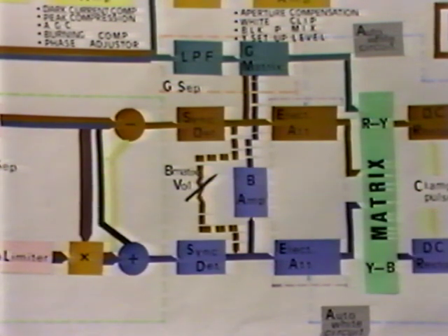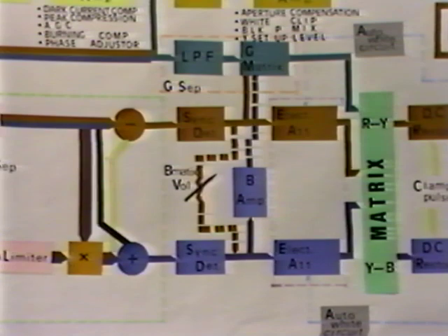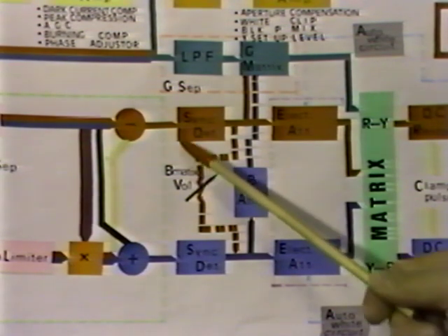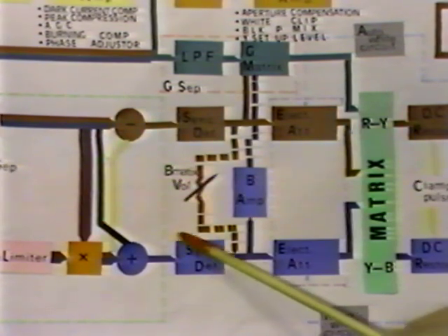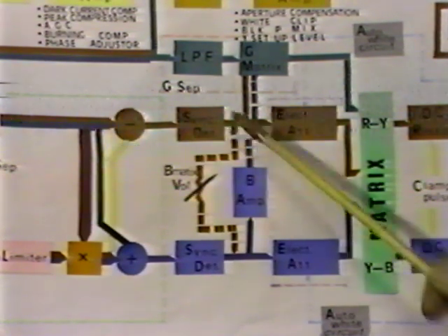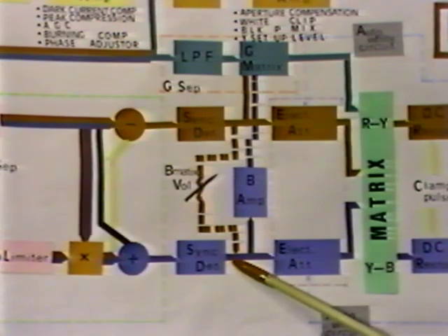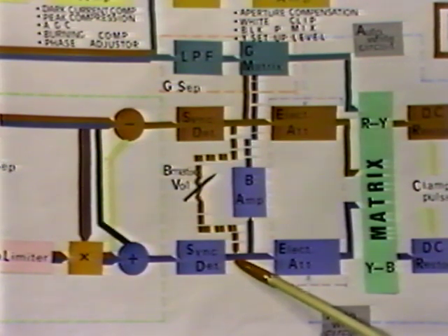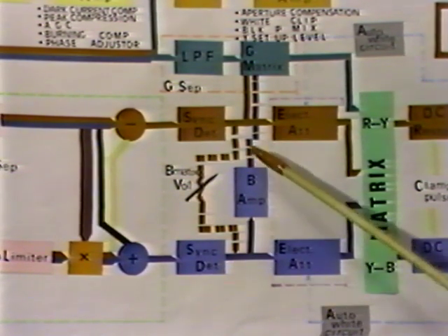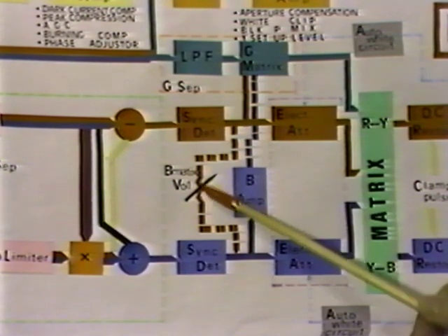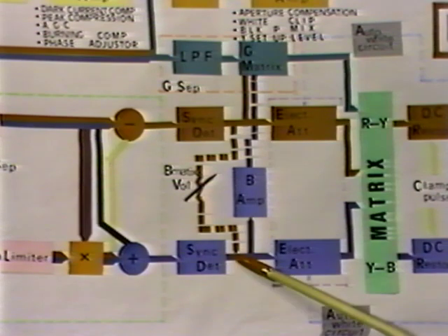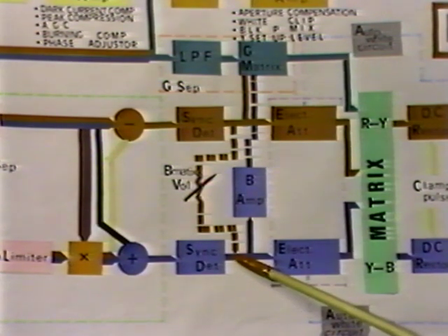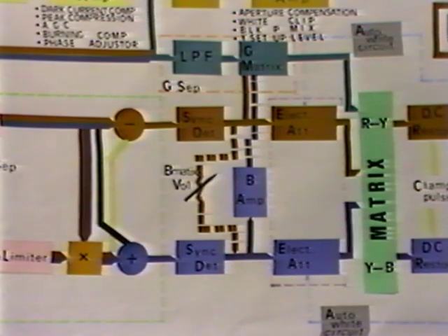This AM wave, amplitude modulated according to the intensity of light, is detected by the following synchronous detection circuit to produce the R and B primary color image signals according to their amplitude. From the R channel to the B channel, through the B matrix potentiometer, the R signal is added to eliminate the R signal disturbance on the B channel so that better color reproducibility is expected.